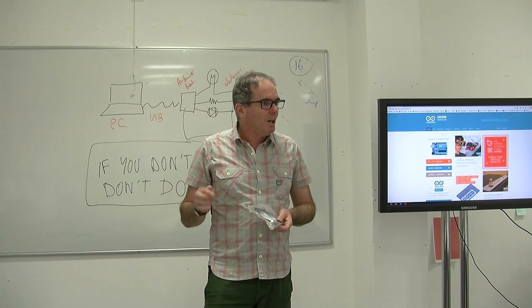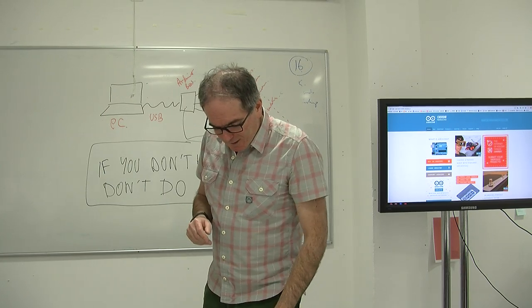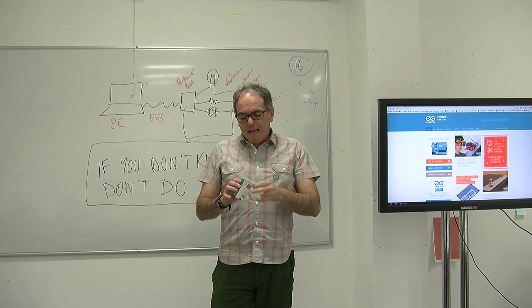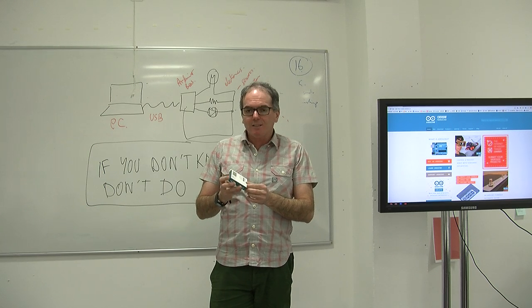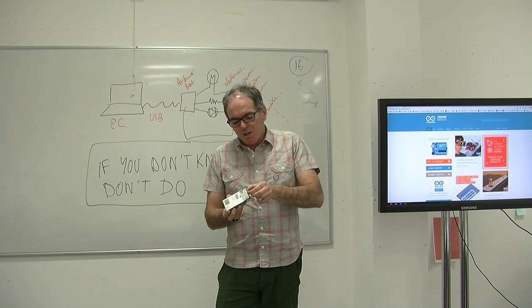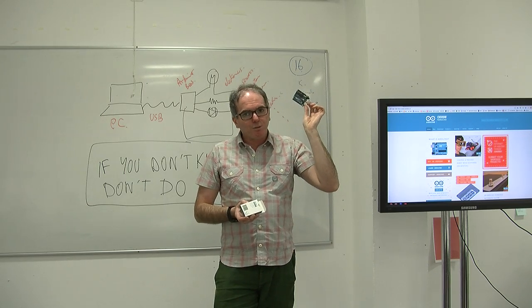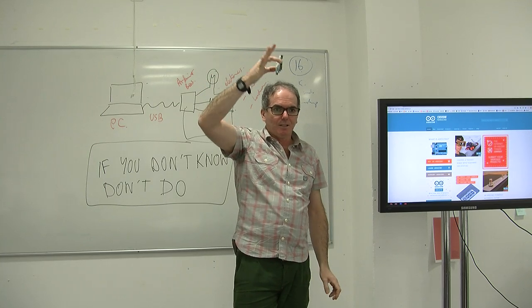It's not going to kill you, but it's going to damage the electronics. Second thing, the Arduino board: you handle it in a certain way. The way to handle it is to pick it from the metallic shelving on the USB port, or to pick it like this.